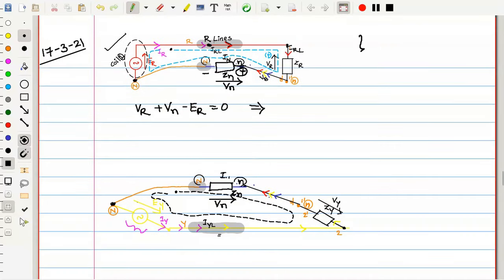Here our objective is to find the line currents first, which I'll write as IL. Once we know the line currents, I can find the IP phase currents. Once we know the phase currents, we can find the neutral current, which is the sum of the line currents or the sum of the phase currents. And after getting the neutral current, we need to find the neutral voltage also, Vn, small n or capital N, whichever notation you adopt. So these are some of the objectives.